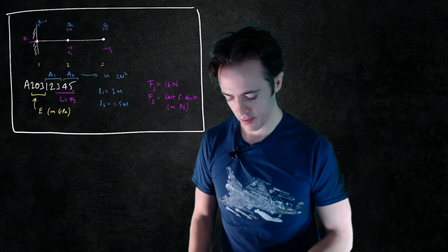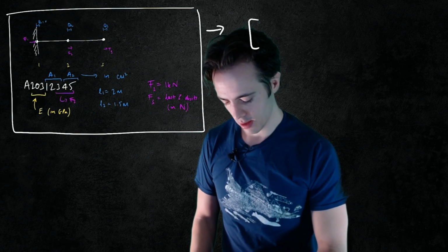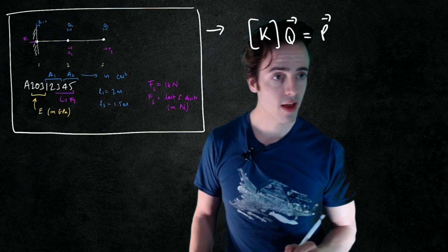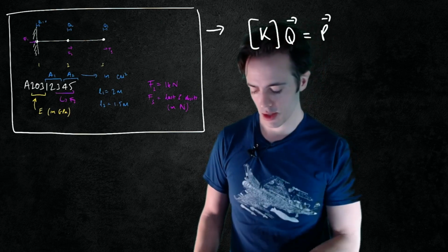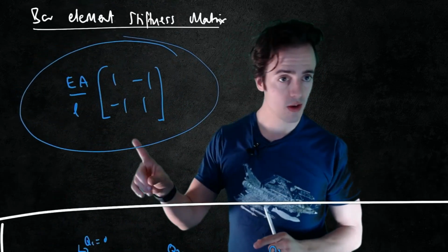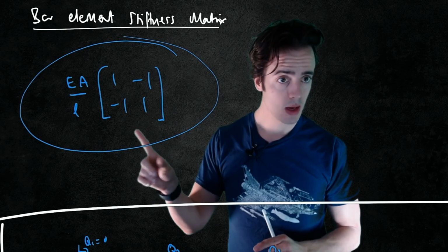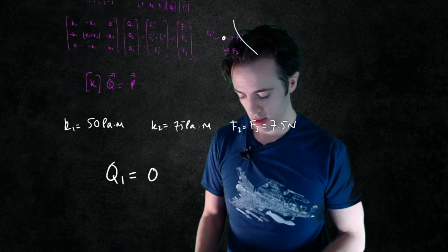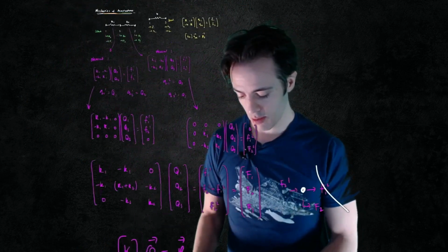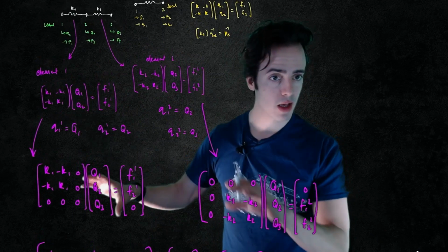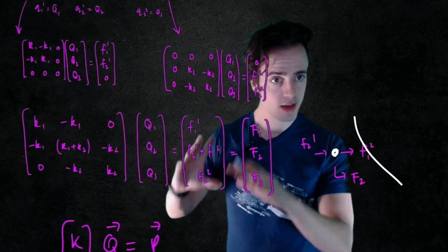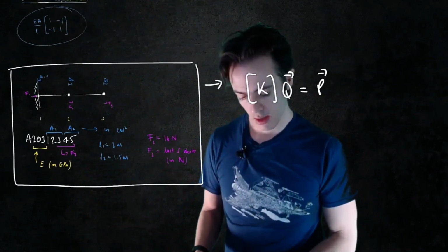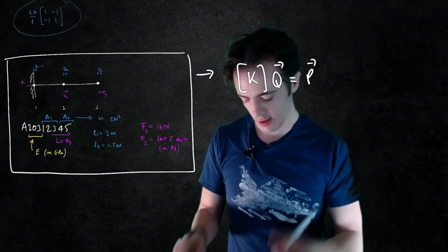I want you to take your inputs, which are defined by this problem here, and I want you to produce the governing matrix that sets up this problem, that solves this problem. So you've got everything to determine your individual stiffness matrices for each spring element, they're now each bar elements, and you then know to go through the same procedure we went through before, where you take each matrix, write it locally, expand it into this format, add them together, get your global system. Okay, so you've now got enough information to do that. So I want you to be able to show me what this looks like.